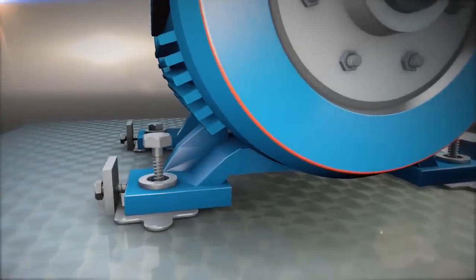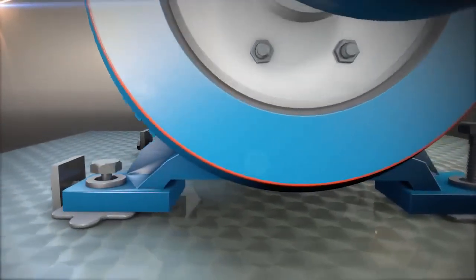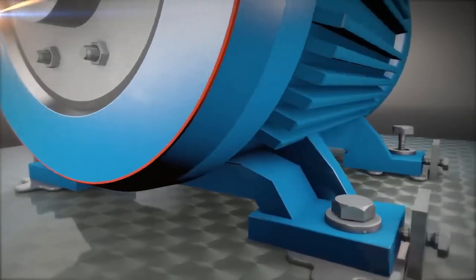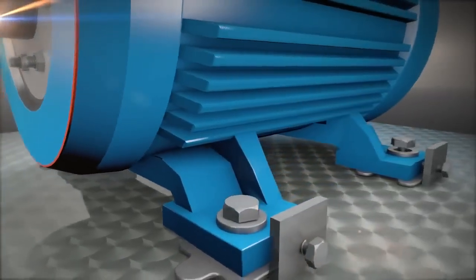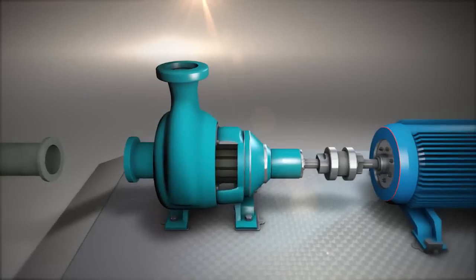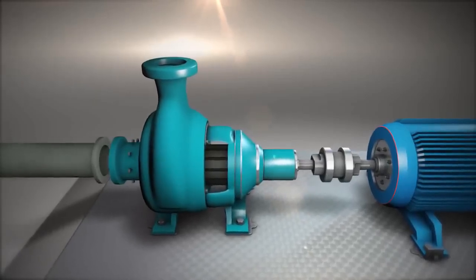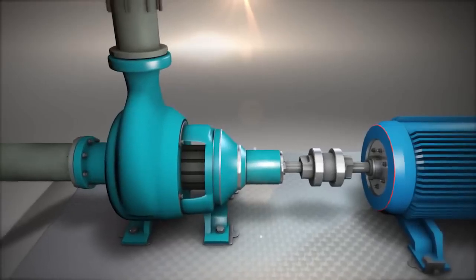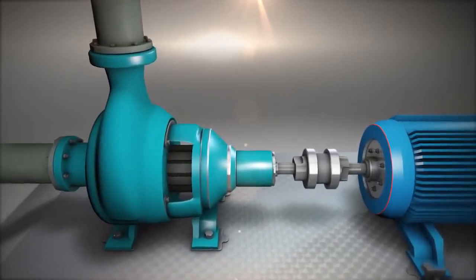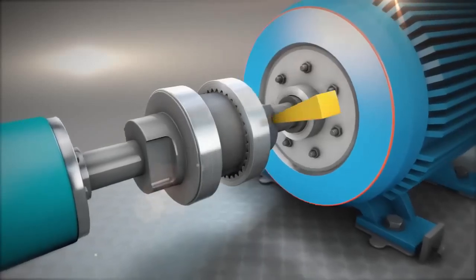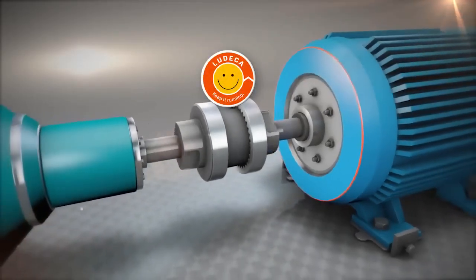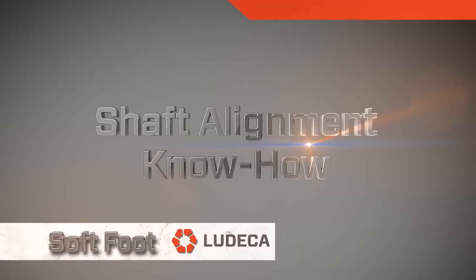Finally, all anchor bolts on the machines should be tightened to the proper torque. Likewise, all pipe fitting should be completed without imposing any stress on the machines. When machinery is properly installed and given reasonable maintenance, the asset's operating life should meet or exceed its life expectancy. A precision alignment of the machines to proper tolerances is required before releasing the asset to operations and being put in service.